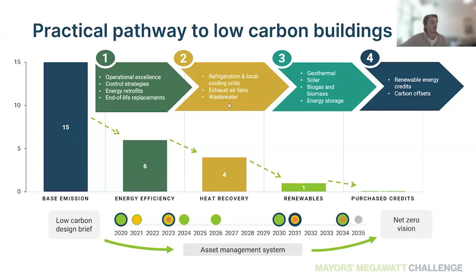Once that's complete, we want to move on to heat recovery. It's not applicable to every building. We work with a lot of hockey arenas, but hockey arenas, grocery stores, anything with large scale cooling, you are dumping or dissipating a lot of heat right out into the environment just to get rid of it. Meanwhile, you're burning natural gas in the adjacent space to heat the lobby. That's obviously not ideal. A big thing we want to look at is recovering that heat to reduce the amount of fossil fuel being burned, or even electricity, the amount of extra energy being used to heat the space.